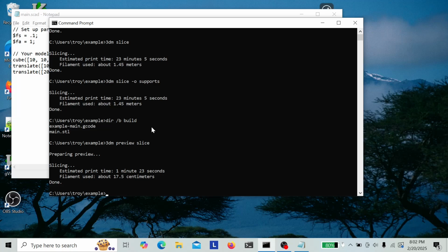And because this is a simple kind of model, you could actually detect whether you like the stair sizes, whether the heights are right, whether the three cubes are connected to each other, just by doing this tactile preview in 2 minutes. And then if you had any issues, you could save yourself the need to do that bad print all the way to completion. So that's something that you can print by doing 3dm preview print or 3dm preview slice print.